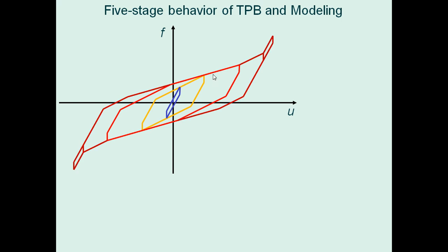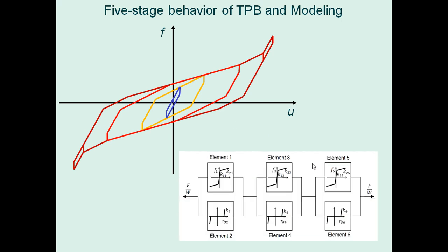Triple friction pendulum bearings are also designed such that they produce the stiffening stages to reduce the displacement limit during very strong earthquakes. This multi-stage behavior can be represented by assemblage of springs shown in this figure. Current elements in analysis software can be used to build this model. However, we found that for three-dimensional behavior, a self-contained element has more reliable convergence properties.